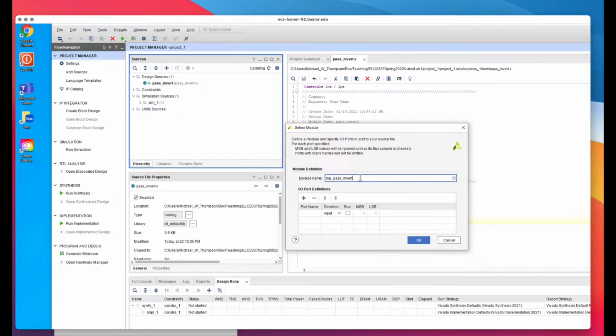All right, so here's where we get to the point where we've drawn a diagram where we know we have switches as an input. All right, this is constrained. This variable name can't be just anything you want. The constraint file is a file that lets the whole system know what the variable names for the switches are and what pins they are connected to.